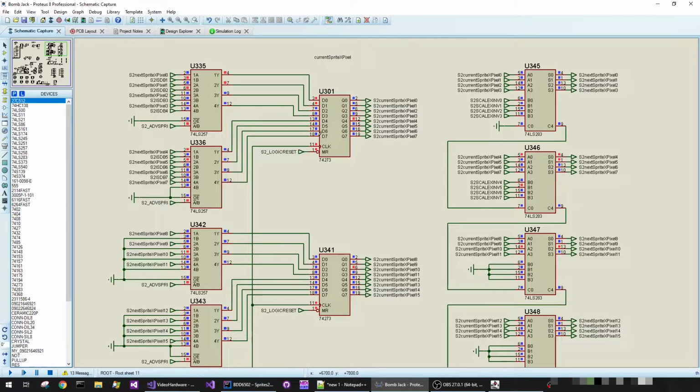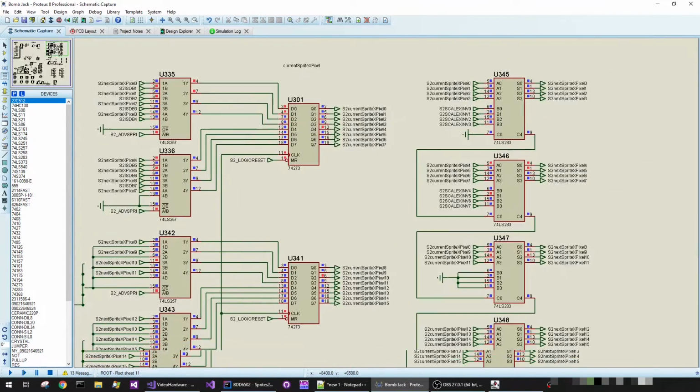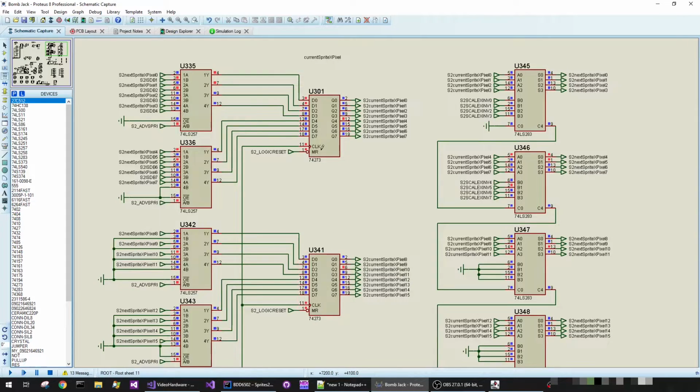So at the beginning of the logic, it reads the value and latches it in two 8-bit registers. Yeah, only two 8-bit registers, it's not too excessive. And the 16-bit value is basically read from what is being presented on the internal data bus, which in this case is basically half the X inverse value and then a bunch of zeros.